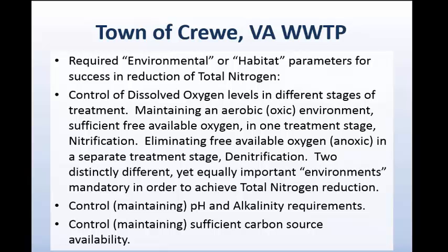In the aerobic stage with plenty of free dissolved oxygen, we have to have ammonia, and that's where we will convert it. The end result is nitrates, and then in the following stage, the anoxic stage, that's where we will remove the nitrates where the ammonia has already been depleted.